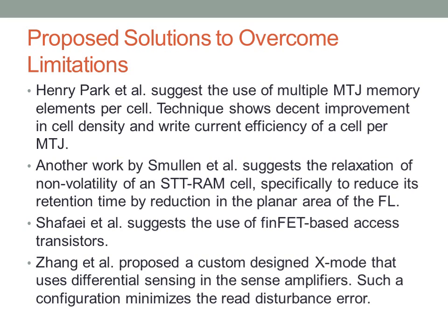Shafai suggests the use of FinFET-based access transistors. Now these transistors, in comparison to MOS-based transistors, show a small improvement in read and write latencies. Zhang proposed a custom-designed sensing mode that uses differential sensing in the sense amplifiers. Such a configuration minimizes the read disturbance error.